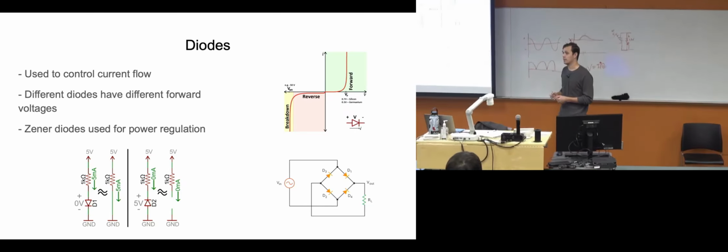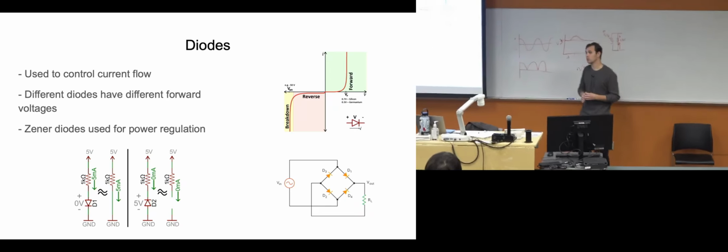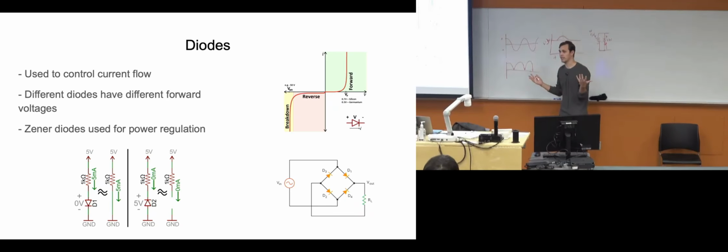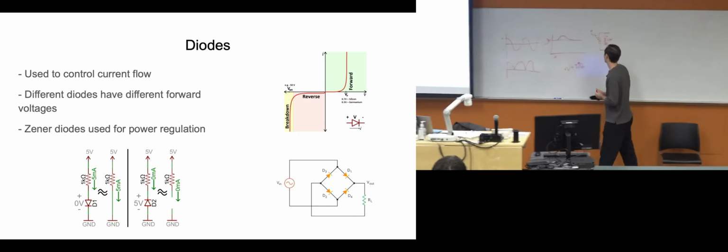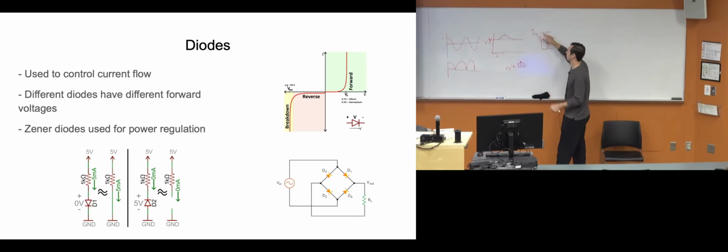Right. Does anyone have any questions? Yeah. It's just the same concept as the fuse. Yeah, pretty similar. Yeah, so like a fuse, if you put too much current through it, it'll break, and then you have an open circuit, right? High impedance. This is just another way. If you had like a fuse through here, if you had too much current, yeah, it would be the same thing.